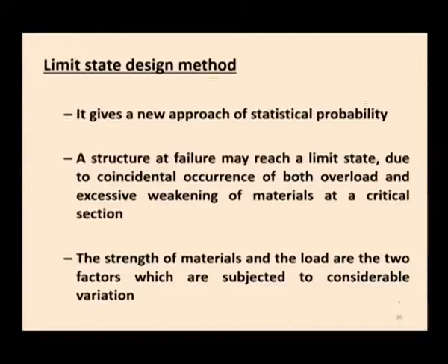In the limit state method, limit state means the acceptable limit for safety and serviceability of the structure before failure occurs. That is the concept of design with such a limit state, so that the structure will not become unfit for use and will not reach the limit state. In the limit state design method, two limit states are used: the limit state of collapse and the limit state of serviceability. The limit state of serviceability was added, so deflection and cracking effects are considered in the limit state method.